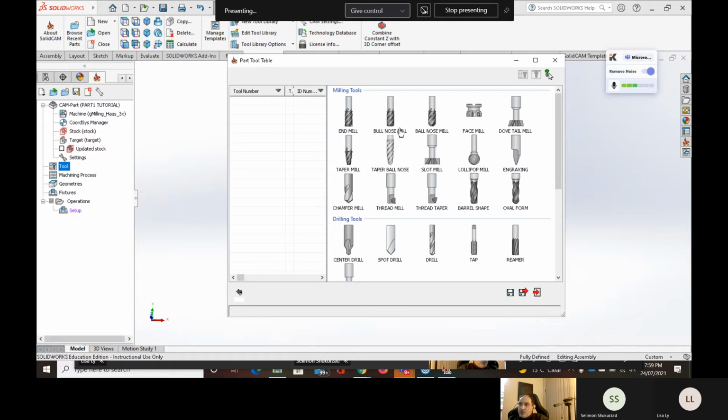Now, the nose ball is not going to give you sharp corners vertically. It's going to make them a little bit rounded. I think you remember why we sometimes needed a little bit rounded, because this will give it more strength rather than sharp corners, edges. And we have the ball nose like that, or the lollipop, and this is going to be able to make the contour shapes.